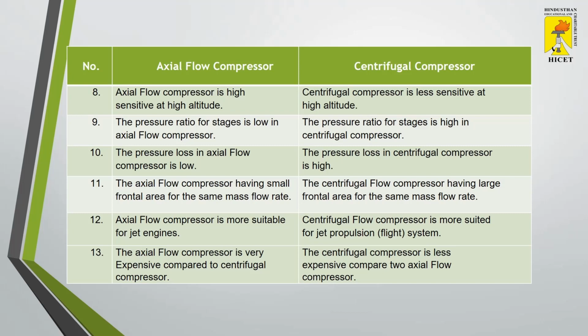The axial flow compressor is more suitable for jet engines than the centrifugal flow compressor because of this one criterion known as the frontal area, which will induce more drag. The axial flow compressor is very expensive when compared to the centrifugal compressor because of its complex nature.